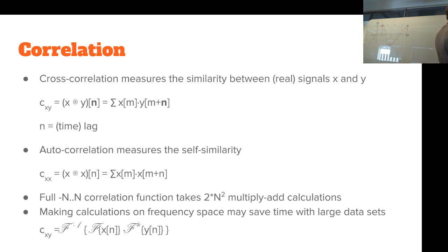And if these signals are totally random, well, that's not a good example. Those are way too complex signals. If you have one bump here and another similar enough bump here, and you start calculating this sum so that you modify the delay on the other signal, you basically get more or less zero until you have delay M, where you have shifted the other signal exactly onto the same position as the first one. Boop. And there we have a high correlation at time shift M.